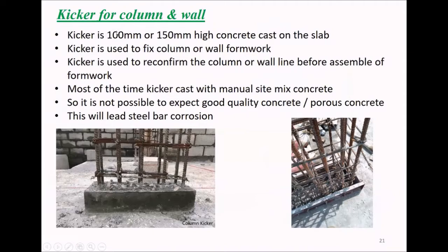Actually, this is 100 millimeter, maybe 150 millimeter high concrete we cast because we want to confirm that the grid lines and the locations are perfect. So we want to confirm. That's why we do these kickers, right? And the column formwork or wall formwork, straight away we can fix to the kicker, very easy. But what we are doing,